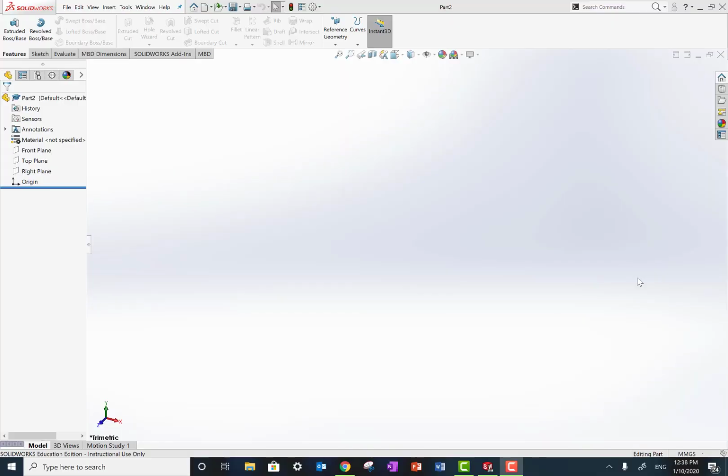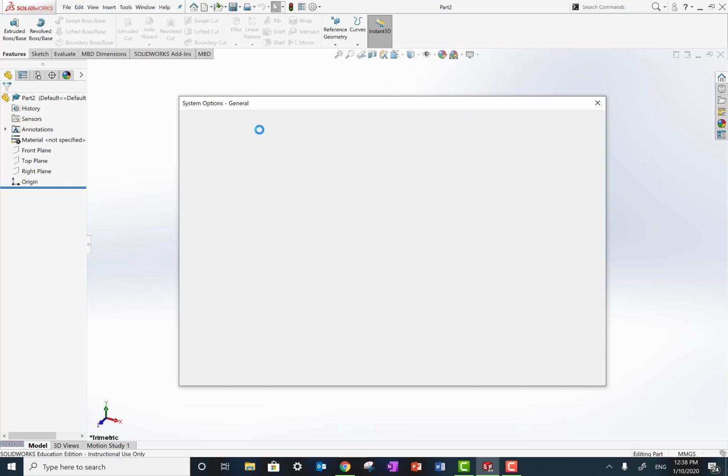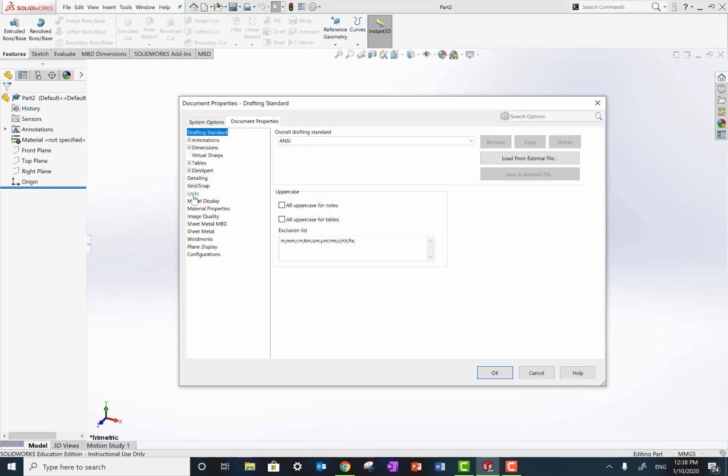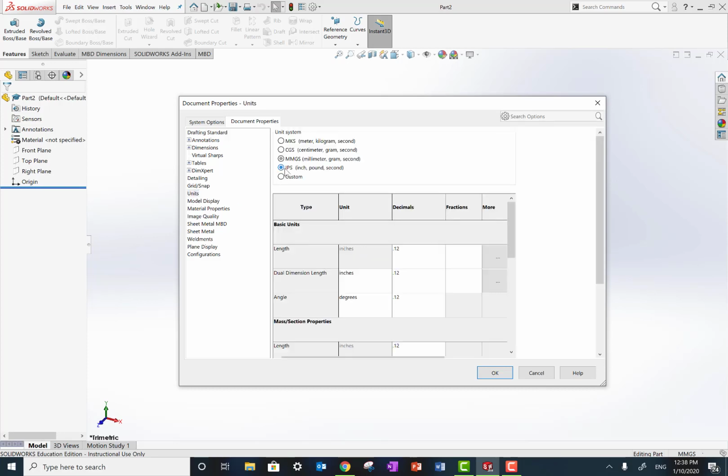In this video, we're going to do a 4x2 Lego in SolidWorks 2019. So we're going to start already in a part. We need to make sure that our units are IPS because Legos were designed in IPS. So let's go to the drop-down menu, Options, Document Properties, and under Units, select IPS, and I like 3 decimal places. Okay, I'm going to click OK. Make sure you make this change before you start.